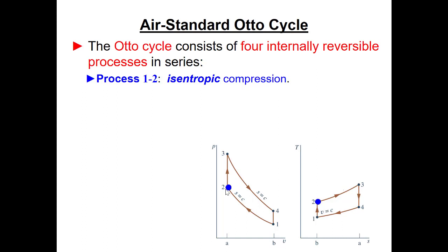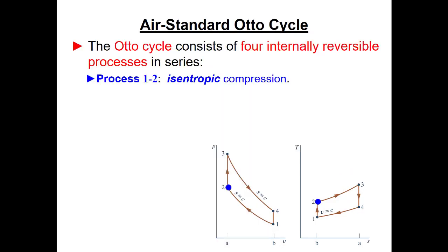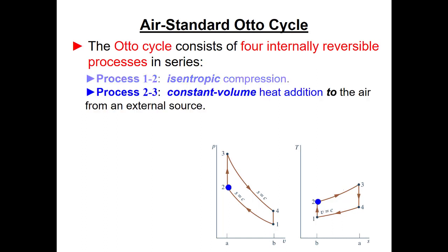We're compressing the fluid. This is the compression stroke, right? Now on our TS diagram, because here we're putting work into the fluid, we assume this is adiabatic. So this is one of those isentropic processes we were talking about. One of the keys to being able to solve this system is recognizing which processes are isentropic. So it helps to be able to draw a TS diagram here.